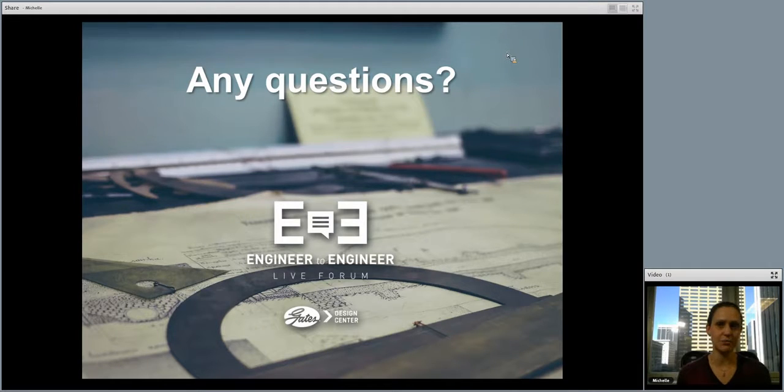Another question, does NEMA apply to gearboxes? No, NEMA diameters only apply to electric motors. However, you do want to check with your gearbox manufacturer. They use something called overhung load. So you want to take the drive and check with your gearbox manufacturer to make sure that the shaft loading is within the limits that they set.